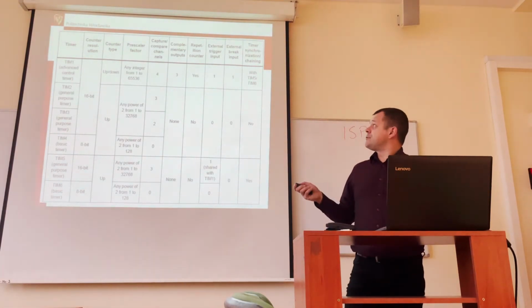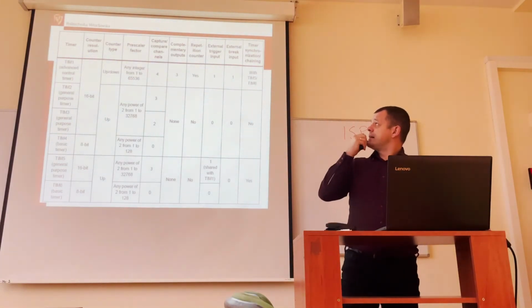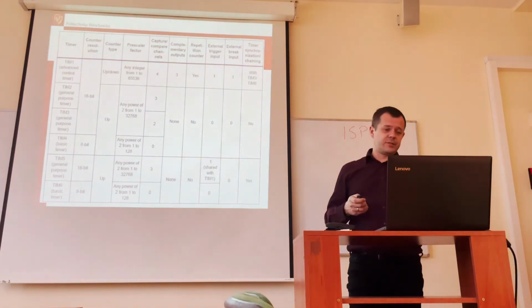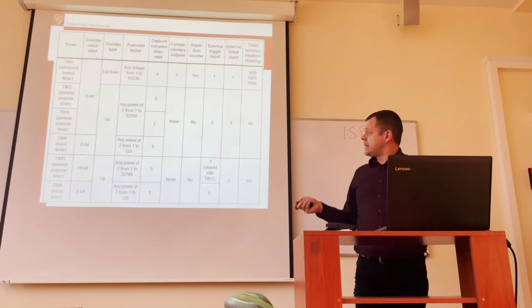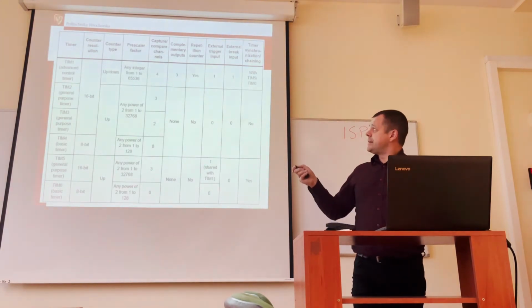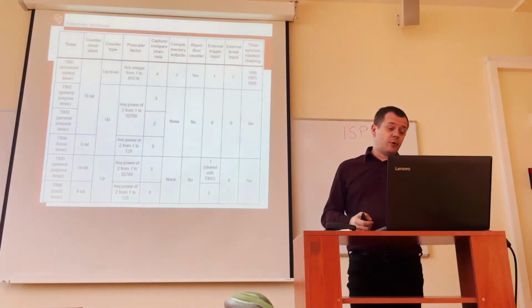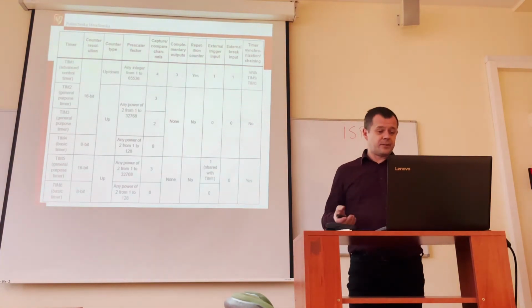It means that we have dedicated registers available besides the main counting register inside the structure. The number of compare channels may differ, and usually differs. Here, the simplest ones, the 8-bit ones, have no capture/compare functionality.